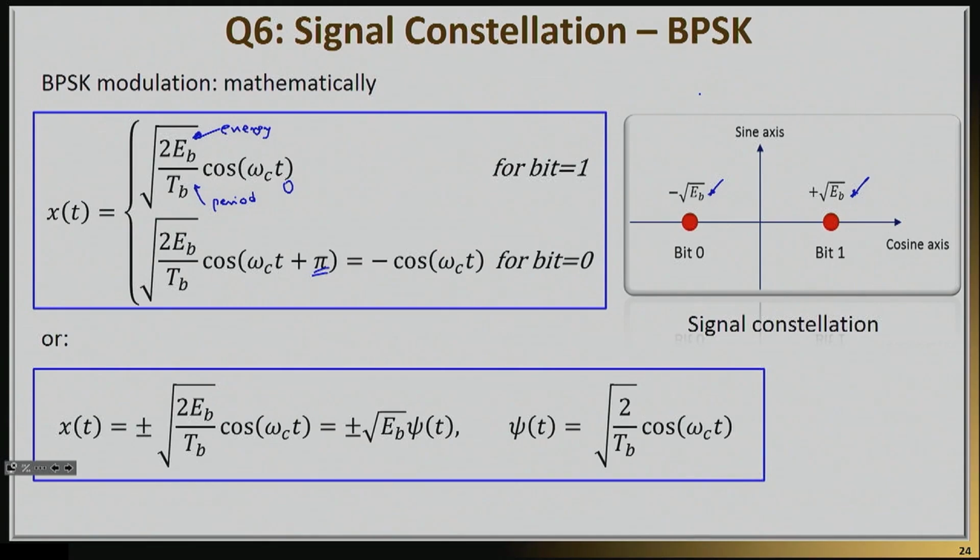And that's basically it. Now, the reason this becomes quite useful is that we now have a basis function, which is my cosine, and we can expand all the signals of that modulation scheme along this basis function. In more complex cases, we need the sine as well to expand the signal, not just the cosine. But in the single BPSK modulation scheme, the cosine is sufficient.